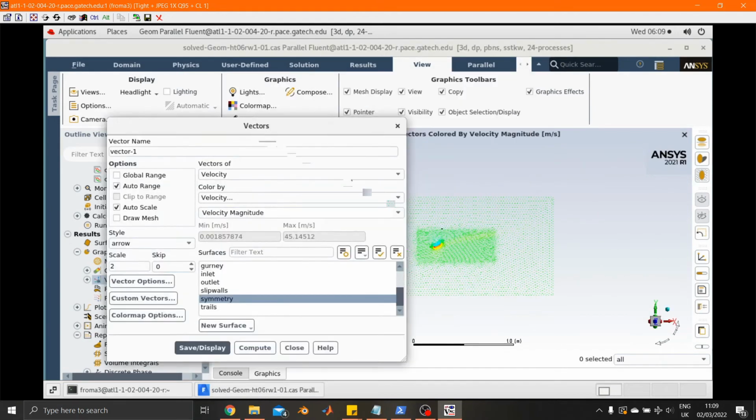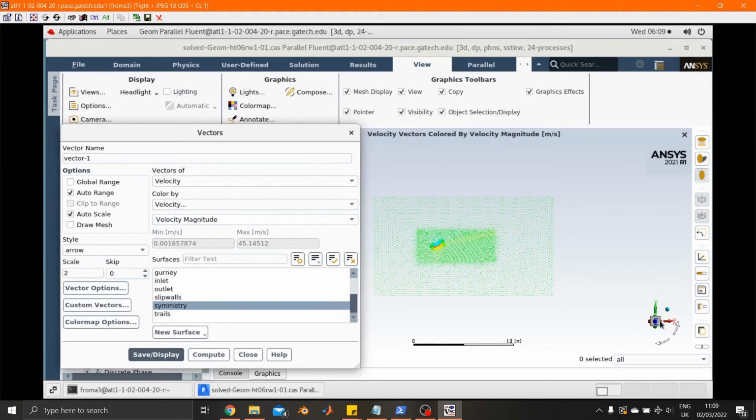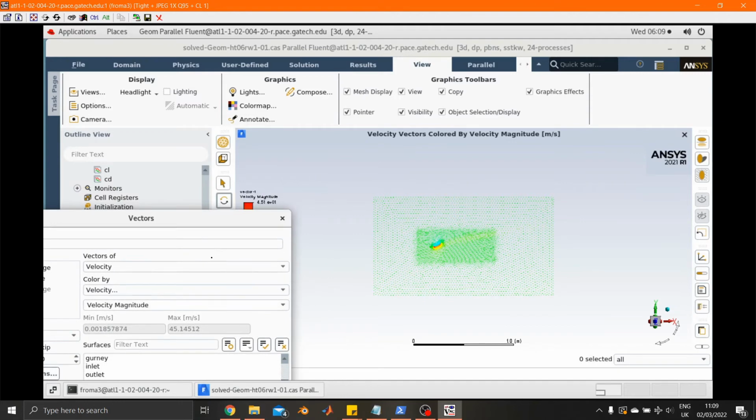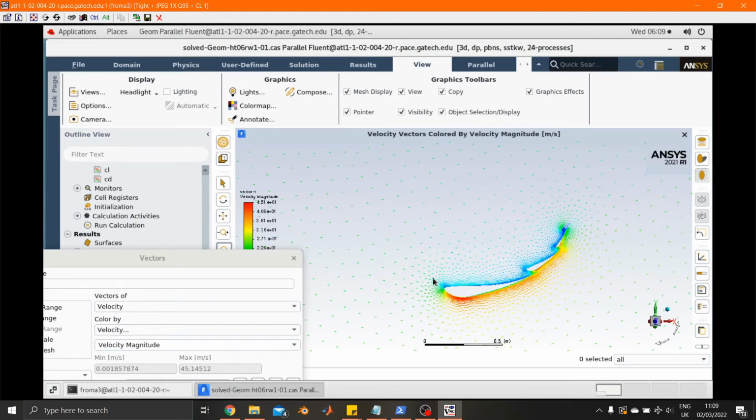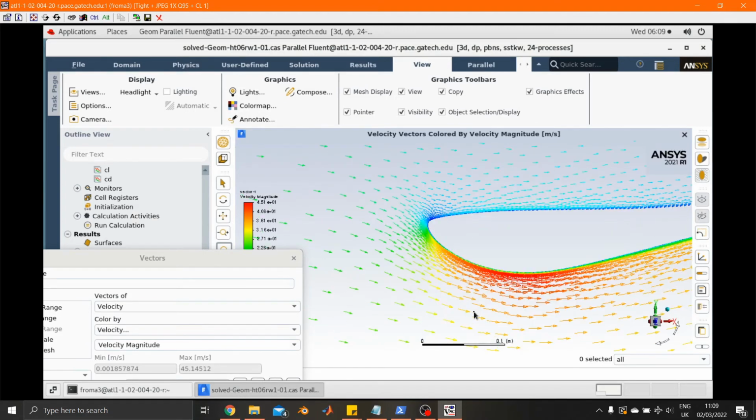There we go. So you can click any direction on this little compass down here, and it'll switch the view to that direction. And now, if I zoom into the middle, you'll see these aren't actually colors, they're arrows. If I zoom in all the way right in there, you can actually see at every point in the flow or in the mesh which direction the flow is going, with what velocity, based on the color and the size. And yeah, you see obviously it slows down here.